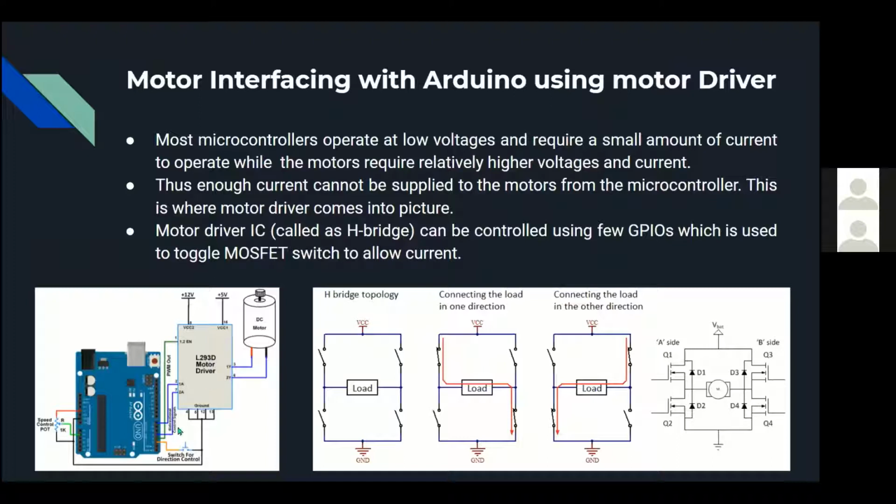This motor driver also comes with two different supplies, namely VCC1 and VCC2. So why are there two different supplies? It's because your microcontroller should first talk with the L293D motor driver to tell it whether your motor should run in the forward direction or the backward direction. In order to have that communication, you need to power up the motor driver's control circuit. Those control circuits will be powered by a supply named VCC1.